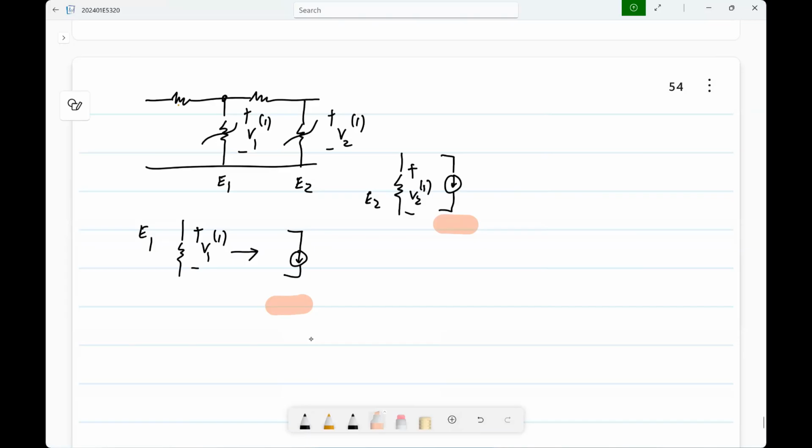Okay. But we are not analyzing nonlinear circuits at any step. We are only analyzing linear circuits. Nonlinearity of nonlinear elements appears as additional sources in every step. So, sources you have to calculate newly in every step. The sources are based on the nonlinearity. Analysis is of a linear circuit. In fact, it is the same linear circuit. Right. Any questions?